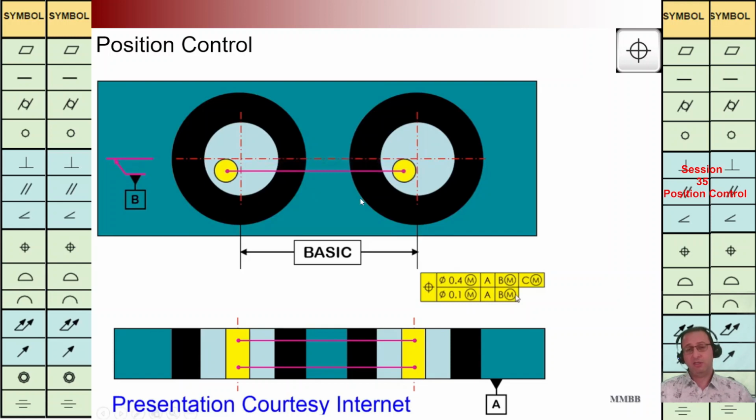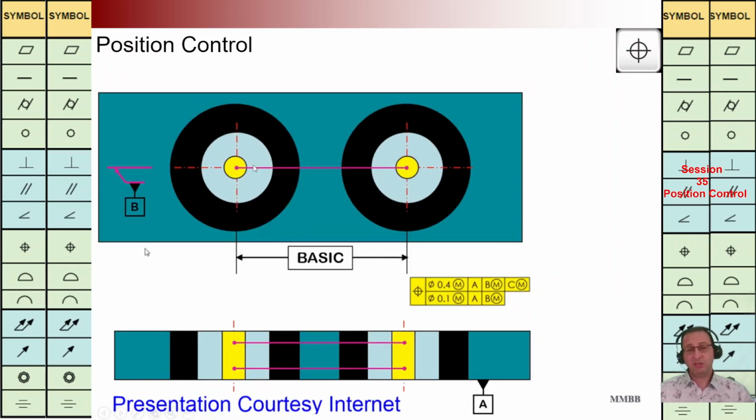For sure, center to center of these two small cylinders has this value, this basic dimension, and we are going to have an offset with respect to B, and these two small cylinders should be in contact with plane B. They can be in this situation, as we can see, they can be tangent to that, or they can be in this situation, and also they should be perpendicular to A.